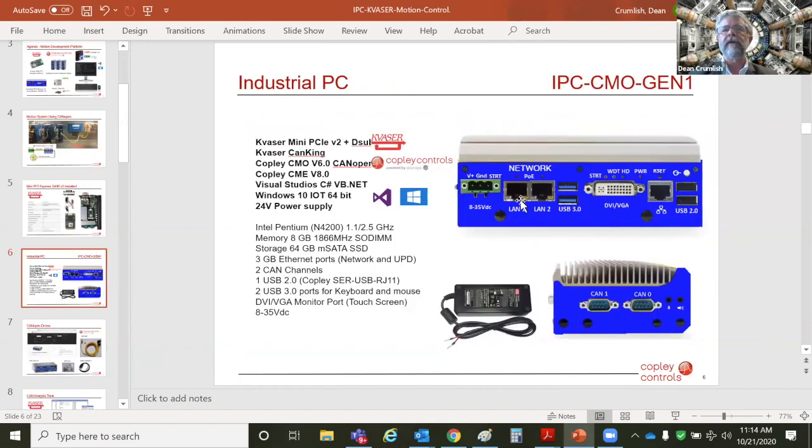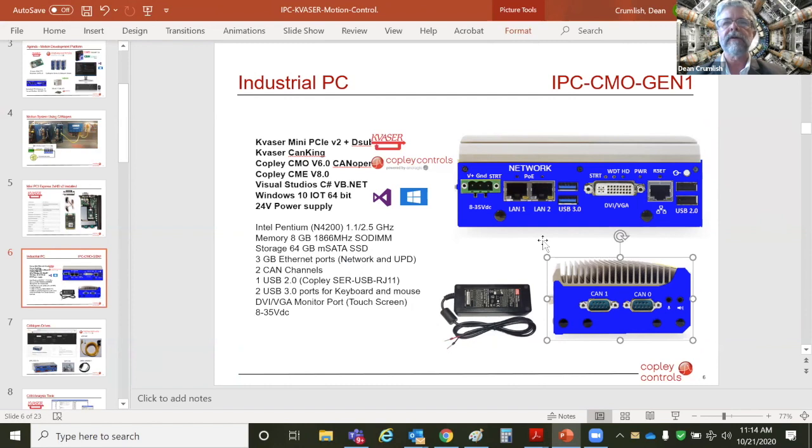This is just a typical industrial PC. You know, it's a computer without a fan. This one is a Neosys, but the distributors tend to have a brand like Advantech or whoever they recommend. This one was used on a tugboat. You plug in your monitor and keyboards, and you can even hook it up to your corporate network. But out of the side here, there were two plates that were punched out, and the cable was put in.